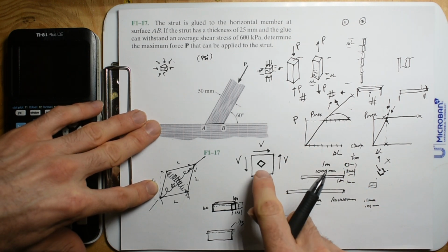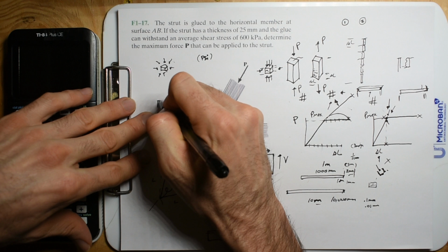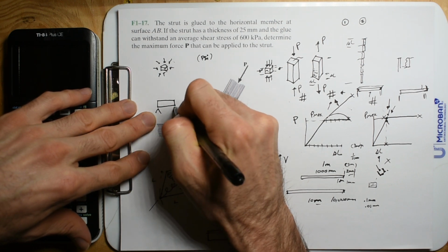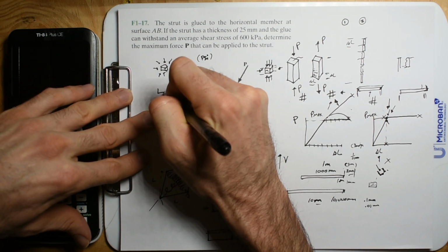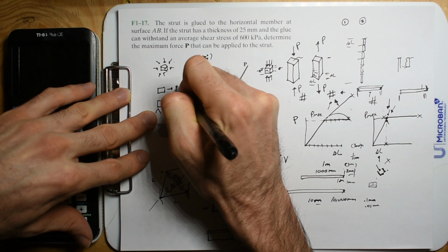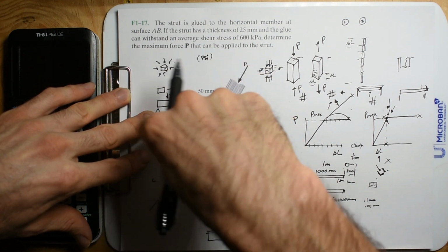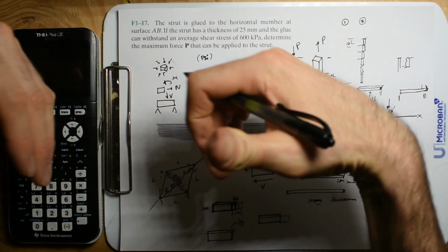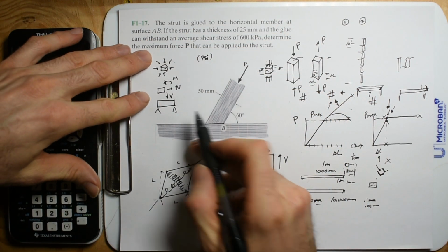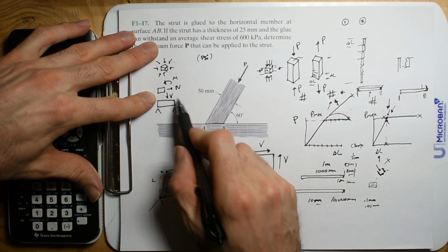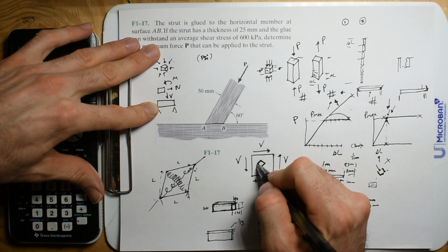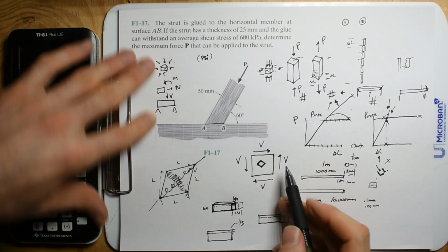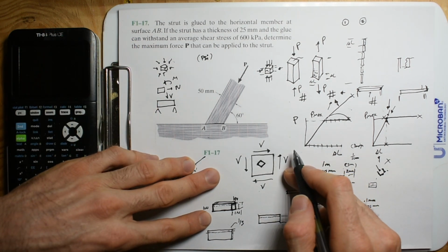I mean, you think you're good at taking a beam, doing the reactions, and then cutting it in two, and then having a normal force, a shear force that causes a clockwise rotation, and then a moment that would cause it to smiley face, you know what I mean? Even if you're just stellar at that, I think it's a challenge to take this diagram,